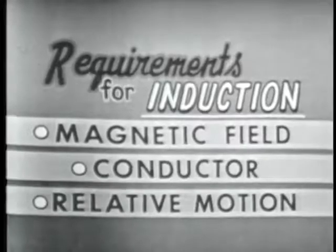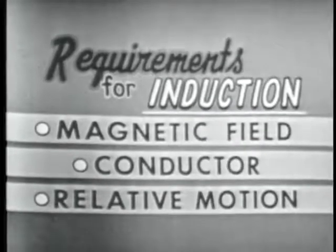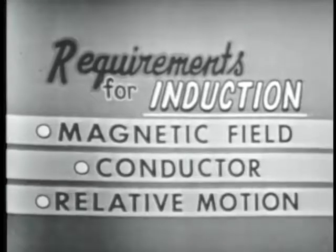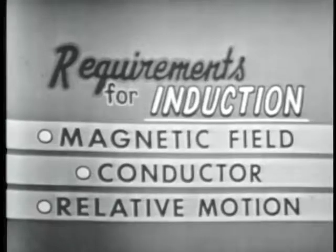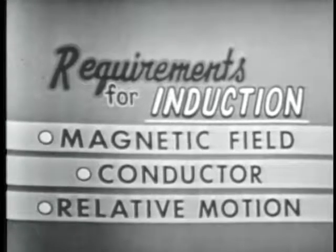But, Bob, how fast does the rotor turn? Well, to answer that one, we've got to reconsider the requirements for induction. You remember the requirements? I sure do. Magnetic field, a conductor, and relative motion. Now, this relative motion is between the magnetic field and the conductor. And, of course, if there's no relative motion, then there's no induction. That's right. So we know from that, then, that the rotor cannot turn as fast as the magnetic field, because if they were both turning at the same speed, there would be no relative motion between them. No relative motion, no induction.